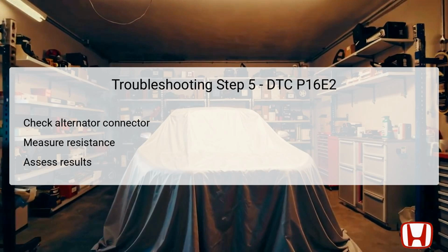Test point 1 will involve the female terminal number 1 of the alternator connector, while test point 2 must connect to body ground. The results from this test will dictate the next steps in troubleshooting based on whether the resistance found is 1 megaohm or more.